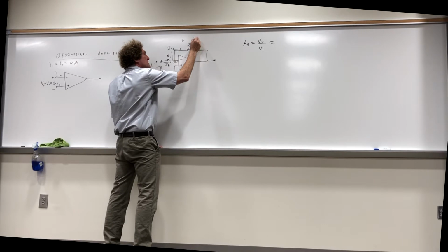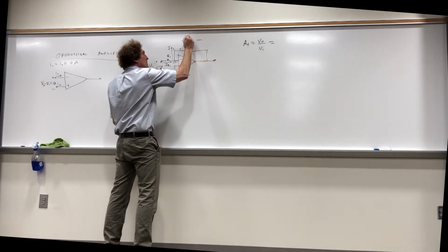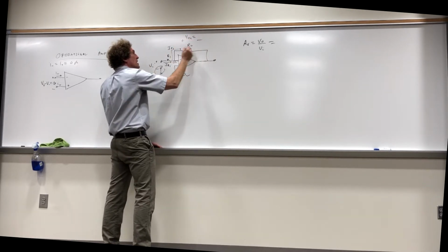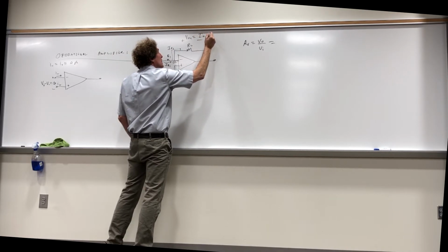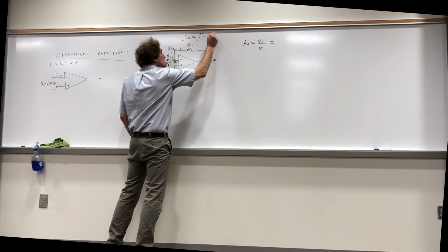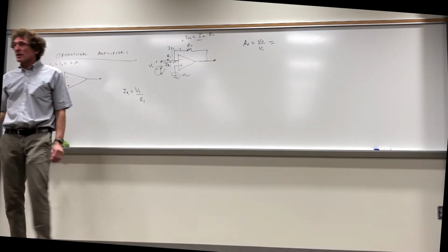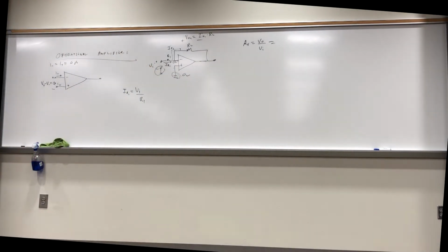That means this voltage here, which we can call VR2, is simply going to be IR1 times R2. Correct, class? Everybody agree? I made sure I did the polarity this way. This is a typical mistake that happens, which I'm about to show you. Do you all see that, class? Maybe I should write a little larger.